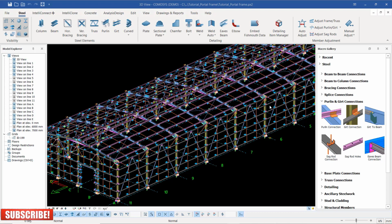Today I want to show you how we can create numbers for our model. Remember, before you generate any drawing, first of all, you have to mark all the parts of your model so that when you submit the drawing to the workshop, they will use the numbers to do the fabrication and also to assemble all the parts on site.